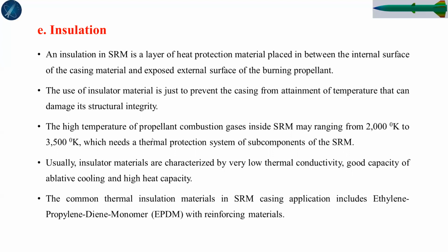It is a material with high heat resistance, so that the insulation itself does not burn. The temperature of propellant combustion gas inside a solid rocket motor ranges from 2000 to 3500 K. This is the combustion chamber temperature, which needs a thermal protection system.